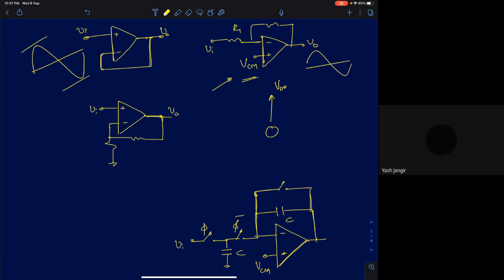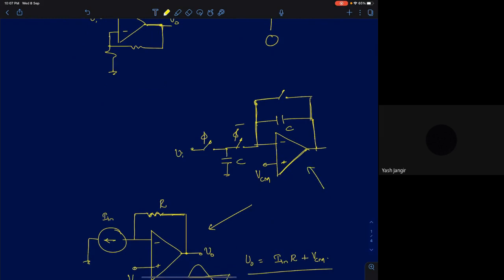If you look at this operational amplifier circuit, which is used in a switched capacitor circuit, in some half of a cycle, or a fraction of a cycle, the input and output are shorted. So this terminal and this terminal are shorted. So your output will be equal to VCM itself for a very short duration. Under these conditions, how does one ensure that I get the maximum gain, bandwidth, and voltage swing out of this op amp? Does it depend upon the common mode voltages? If so, how does it depend upon it? All those questions will be answered when we look at the circuit realizations of these op amps.